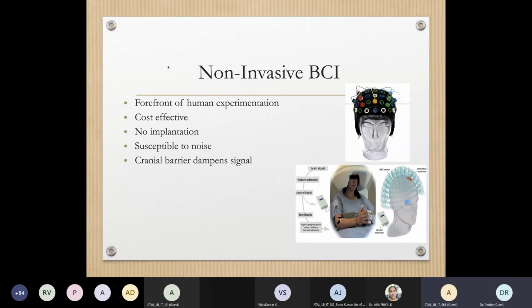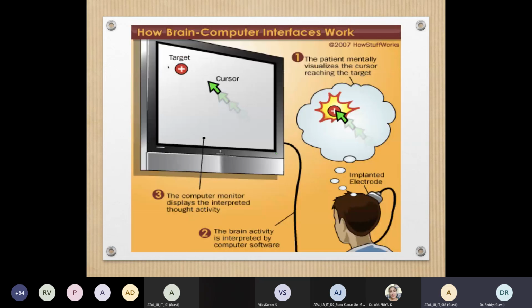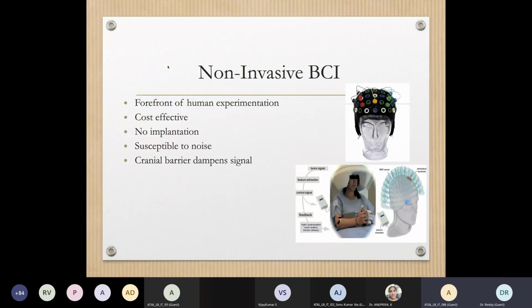Now, once you know the channel, like this green or blue or white one, you identify the channel according to the figure already shown, like T7, T8, P7, P8. If you see the temporal lobe, we already talked about it being close to the hearing function, close to your ears. So T7, T8 means you are towards your ear side, then you place the electrode exactly in the channel position, get the electrodes connected, and then get the signals once your amplifier is on.